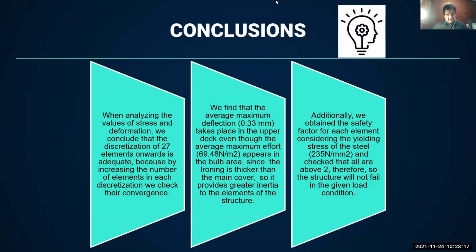So for that reason, as we can see, the security factors are above 2 for all the elements. We can be certain that this structure will not fail for this load condition.